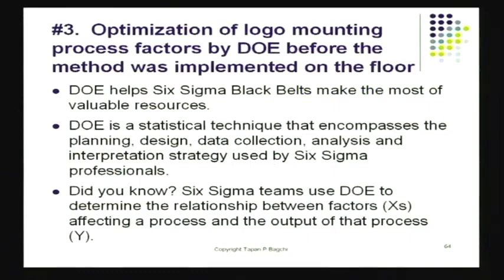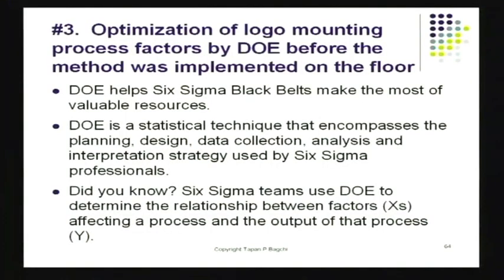I would have probably gone through this, and I would have probably located that the logo might fall off because of improper sticking, or not enough area, or not the right kind of glue, or the logo being too heavy, or whatever it is. I would have probably discovered that if I had done FMEA. That's something that apparently was not done when this was done. The third thing is, I should have actually optimized the mounting process itself. There again, my old friend design of experiments, DOE, comes along.